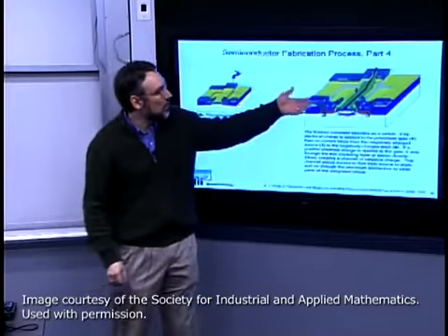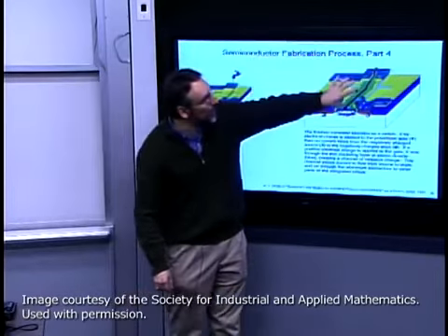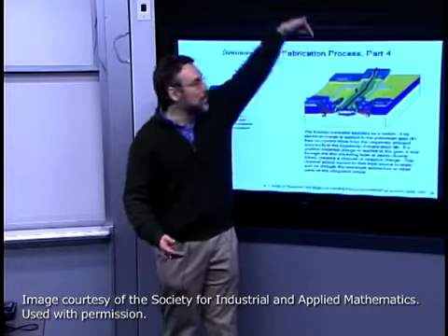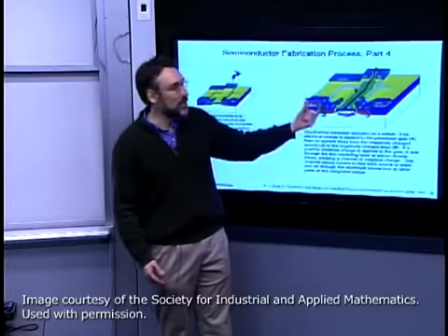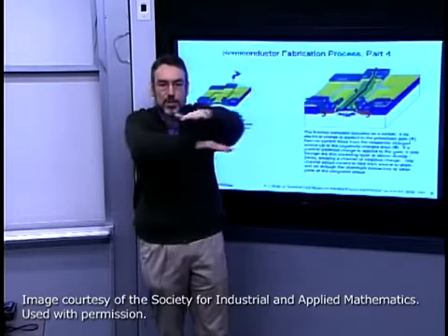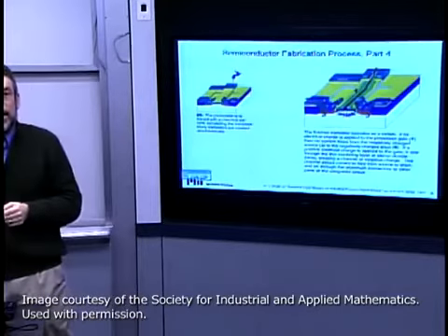And that's where we get to multiple level interconnect structures, where one would deposit another layer of silicon dioxide or other insulator, and then build vertical vias down from one level to the next to contact multiple streets on level 2 with streets on level 1, and so on up to 6, 8, or even 10 levels of metal in modern structures.